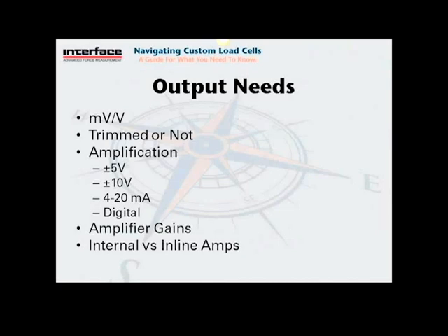Our standard millivolt-per-volt output is largely determined by the load cell design and size, material of the load cell, and a few other things. It's normally fairly consistent. Our manufacturing practices are fairly tight, so we can guarantee that. Normally, all we do for compensation is for zero and offset temperature sensitivity. And for our metrology uses, this is really good practice because you don't really want to tamper with a good output. You will only make it worse.